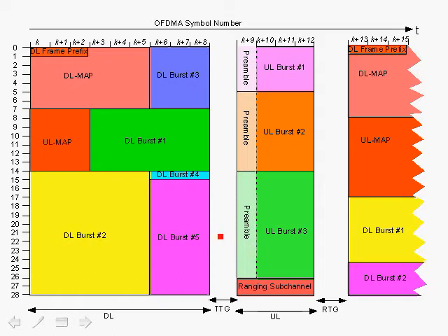In the next slide we are going to describe the actual uplink process, where multiple subscriber stations transmit their data back to the base station, of course based on information they received from the uplink map during the downlink process, in which they know exactly what subchannels, what offset, and how many time slots were allocated to them.